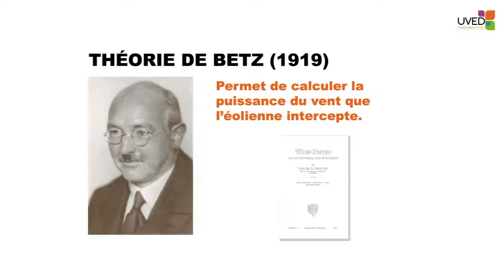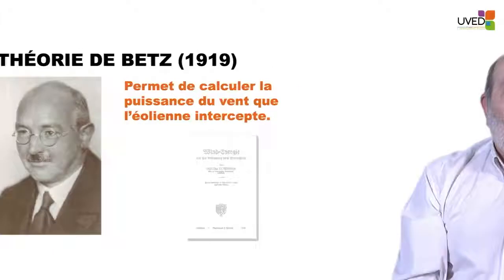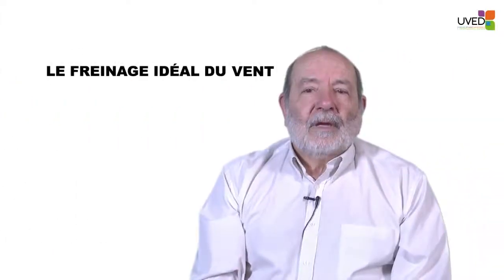In this presentation, we're going to discuss Betz's theory. We'll talk about the airfoil, the lift-to-drag ratio, and we will talk about aerodynamics too. Albert Betz was a German physicist. In 1919, he introduced a theory according to which we can calculate the wind power that is caught by the wind